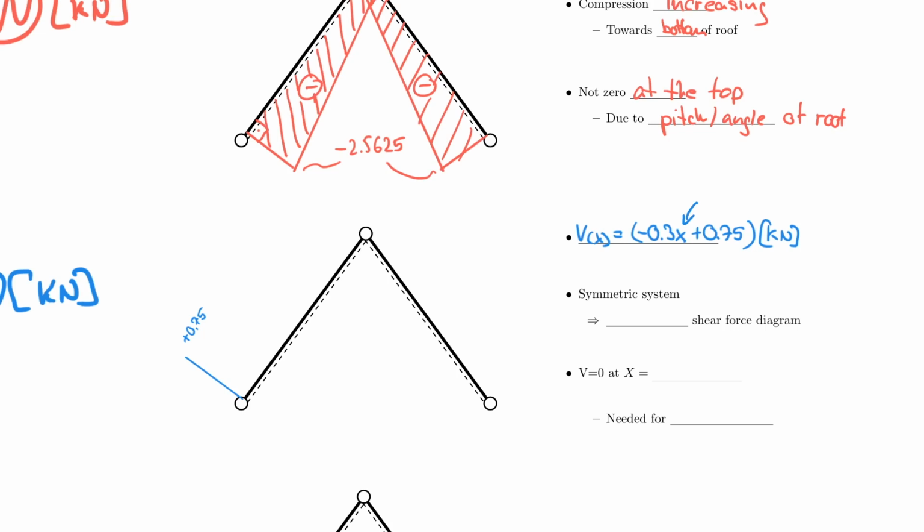And so that's the value I'm going to use here to draw my diagram. So that would be something like this. And I know that it's pretty much an evenly distributed force on there, although it's acting differently than what we've seen before. But I know that it must be linear, therefore. And so I have a positive area here, and I have the negative components here. And if you paid attention, you see it's no different from any beam that had self-weight on it before.